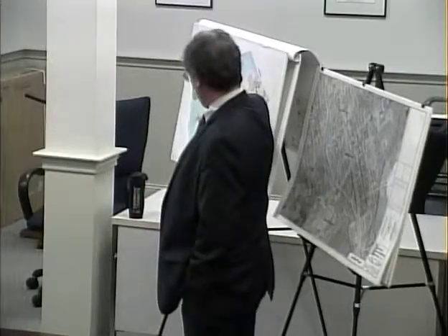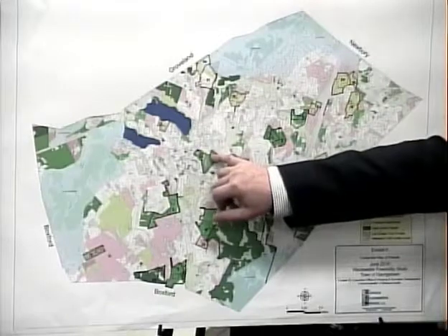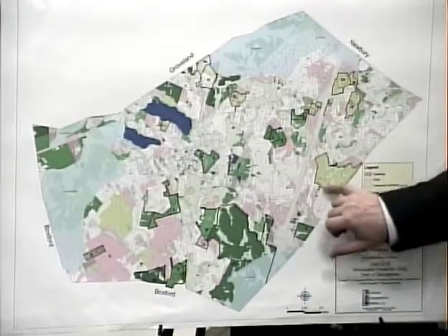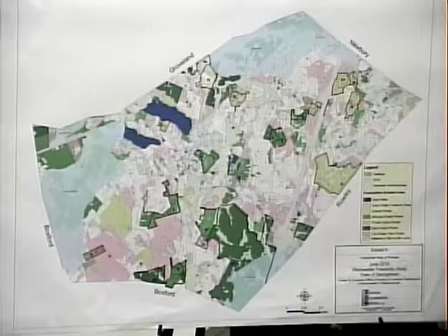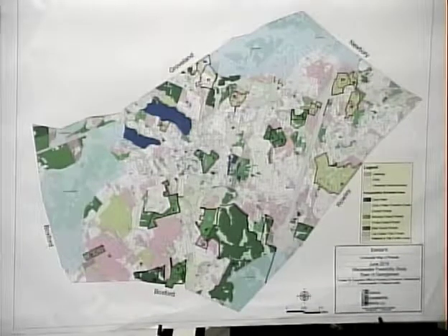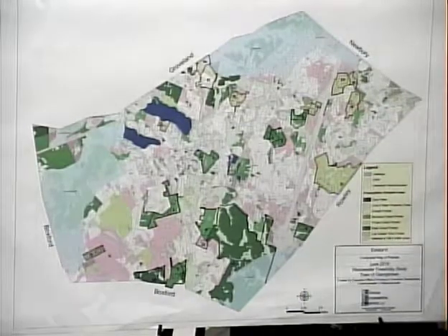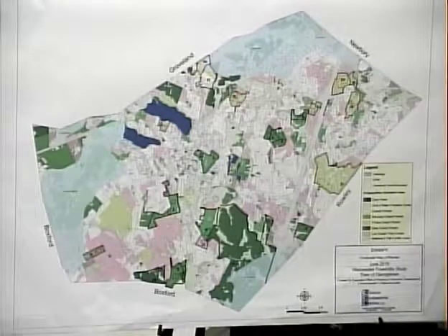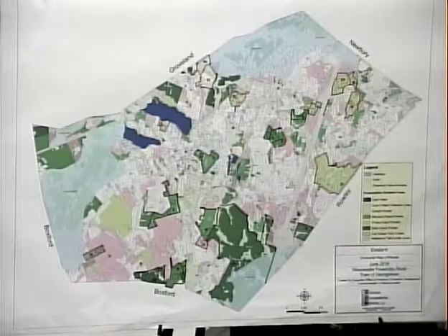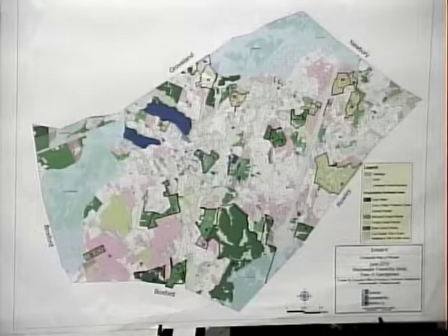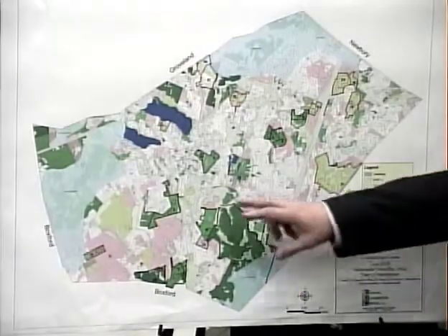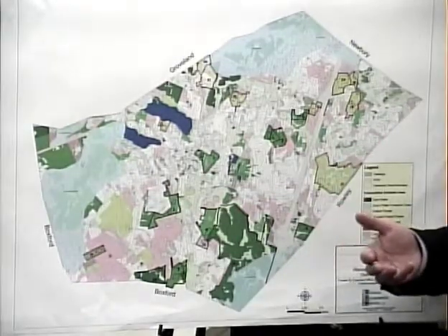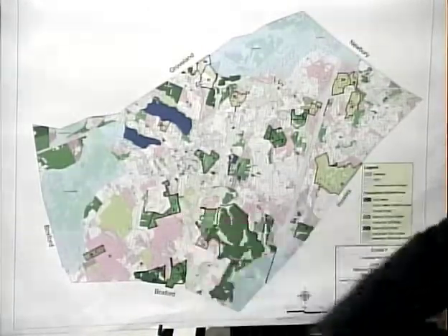There is one little spot at the edge of the property for the middle high school that might be feasible, but what we did is take a look at all of these properties. If you see this, a couple of these have dash lines on them. Those tend to be primary areas that would probably be feasible. Even though these are 5 acre plus lots, some of the areas on there are smaller than that, so the next step after this desktop evaluation is really to do some testing on some of these lots that look most feasible. And that's really going to determine for you, without a doubt, how big the areas you can place on those, the depths of the groundwater mounding that would take place on those properties, and if there's enough land for siting.